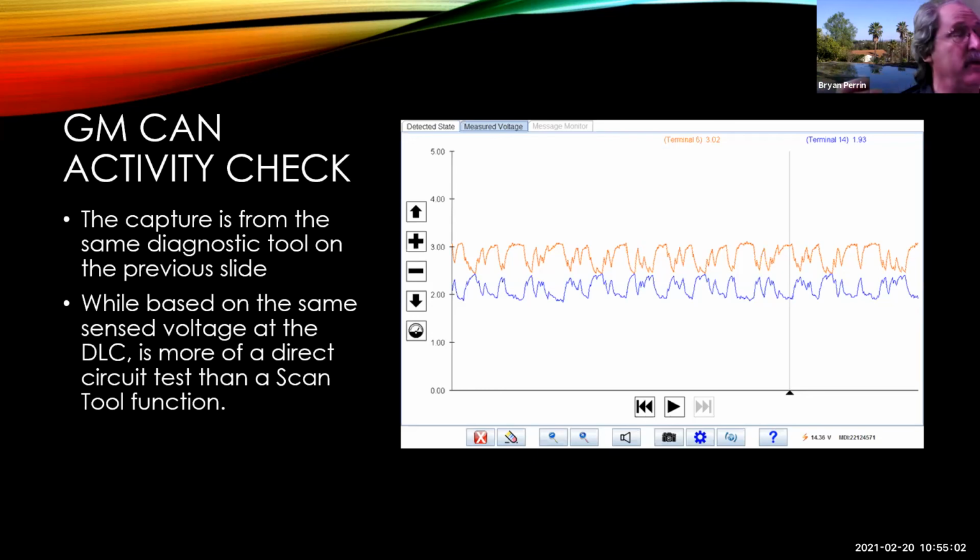And that's why on newer vehicles, you'll actually see not just, hey, problem with CAN low or an open in CAN low, but you'll see it broken down between open or short, not just CAN low is open or shorted, which is what the early codes were. So we're seeing a lot better code definition. You may get both. You may get a code that says it's open or shorted, and then a second code that says it's shorted. So sometimes we get two codes for one fault.